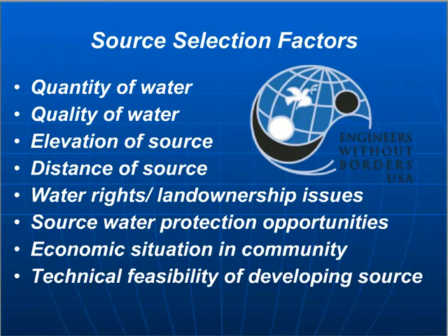So as you're assessing these different source options, here are a variety of different factors to look into. Water quality and quantity are the two most important things, and usually where you start your analysis of your source options. And I'm going to go into a little more detail on those on the subsequent slides. But the other key source selection factors include the elevation of the source, simply knowing: are there any source options out there that provide for a gravity-fed option where you don't need any pumping?